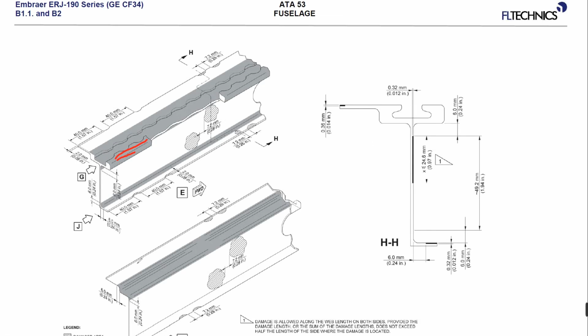So it's not something so dangerous if you scratch the structure of the seat tracks. Just clean and protect. Protect with primer, protect with paint, everything is fine. Okay, just protect. I'm talking about small scratches, of course, but again, please follow the instructions and use plastic scrapers or at least not metal scrapers, not sharp objects.